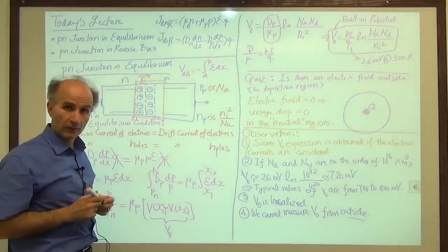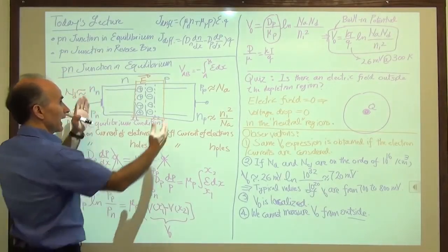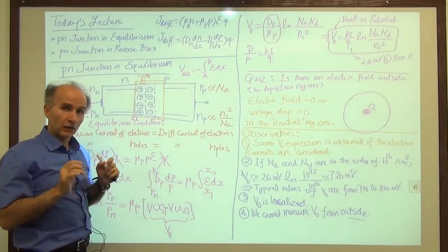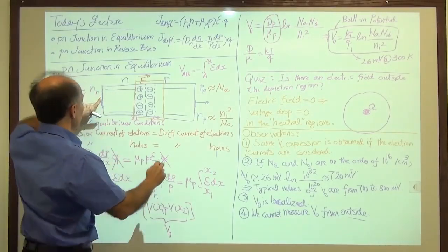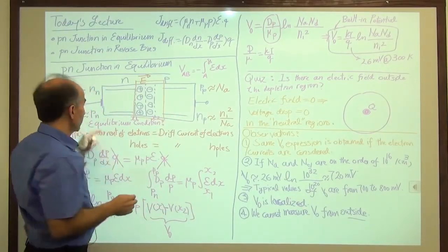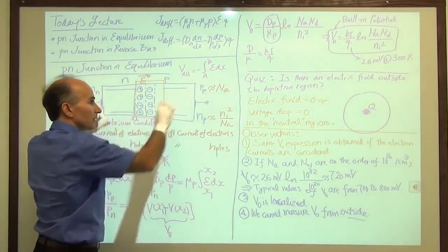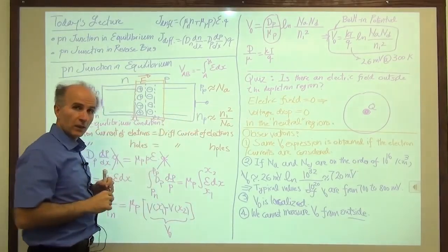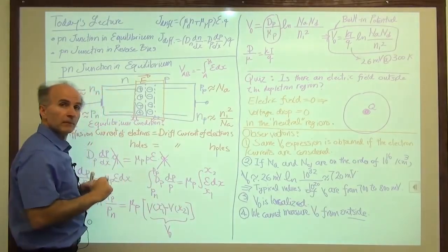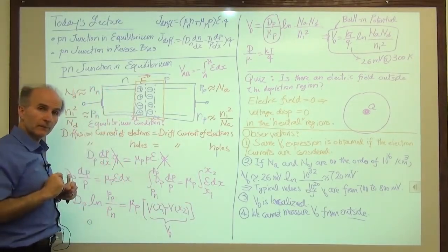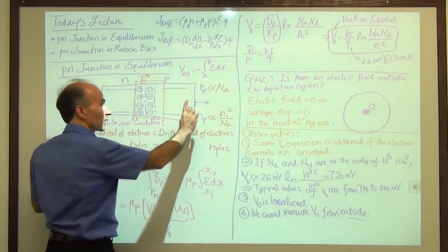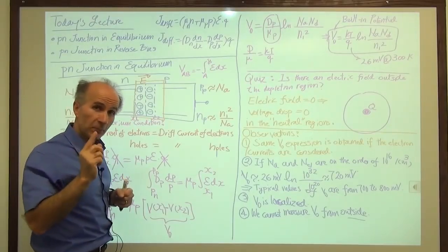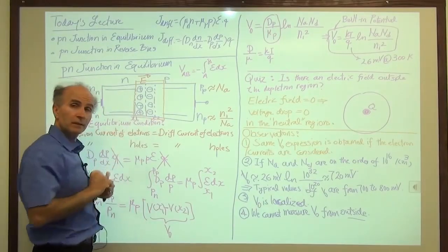So there's a very interesting reason for that. All right, so remember that we have the PN junction formed as a single crystal. Now, to be able to measure anything at these 2 points, we have to connect these pieces of wire to the PN junction. As soon as this wire touches this PN junction, we form another junction here and another junction here. Now, these are not PN junctions because we are connecting a metal to a semiconductor. So it's a different type of junction, but it does have a built-in voltage, just like this junction.